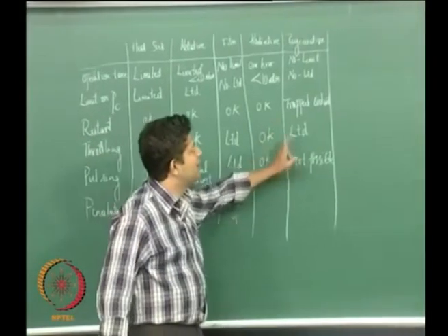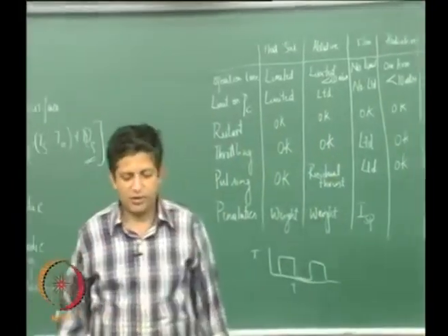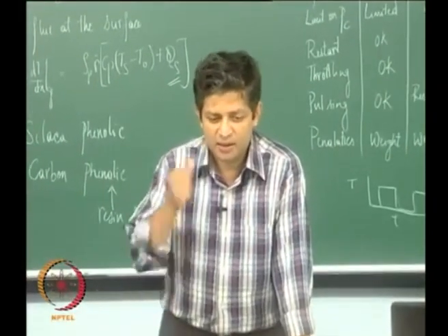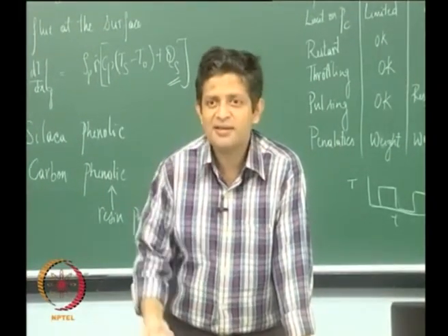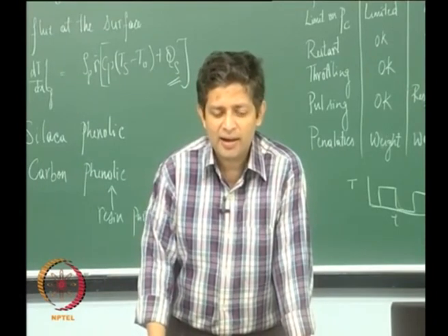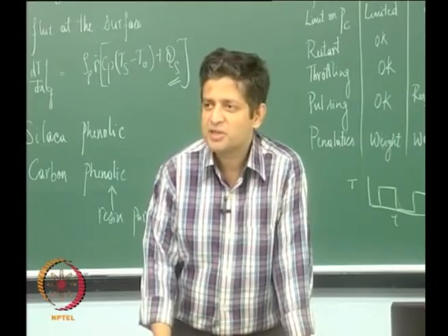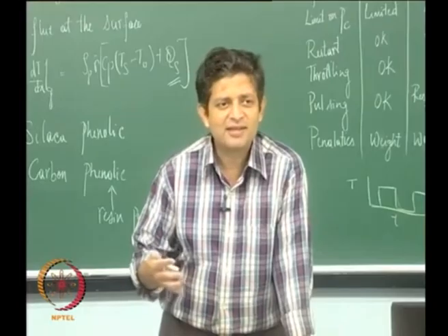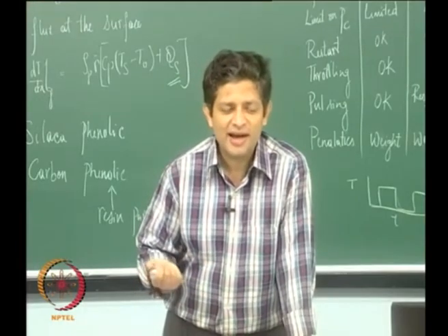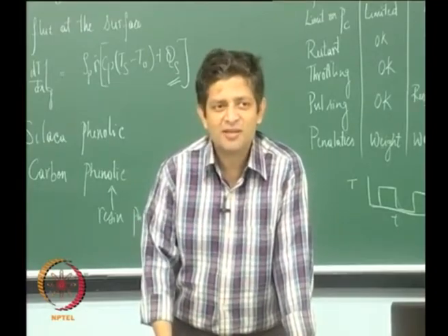Then with regards to regenerative cooling, if you remember, when we talked about it, I said this is mainly for high thrust and long burn duration engines, and I spoke of the space shuttle main engine, which is a liquid engine, where the chamber pressures are of the order of 200 bar, and somewhere in the pipeline it is going to be of the order of 300 bar or above.